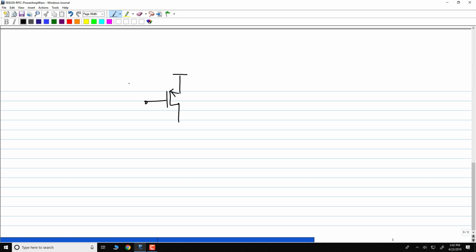Let us say VB2 is already set, it's a current source. Now I can't independently set VB1. I'll have to set VB1 such that it is the correct value for the current generated by this device. This has some current I, and I am trying to pass that through an NMOS. Now one way to do this is, so this is how my signal is coming in.